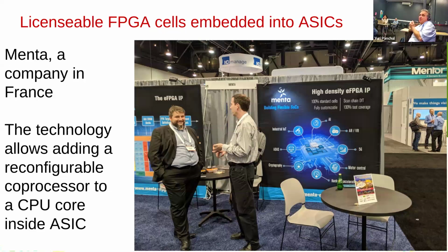But the problem with such startups is that it's difficult to find a good application for it. So they are trying to find a good application by allowing you to add instructions in a small CPU core. Another idea is that suppose a chip designer does not trust the foundry and thinks that the foundry can reverse engineer something. So they put a fixed design in the ASIC, and then they put a flexible design in FPGA cells. This is another idea.